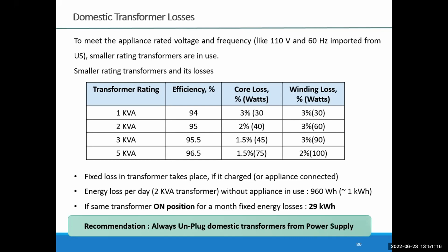Okay, so you're saying that a 5 kVA transformer will lose around 75 watts? A 5 kVA transformer has about 3.5% losses at full load. 1.5, well, no, I'm combining the 1.5 plus 2. Yeah, that is the total losses. That means when we are utilizing this transformer at 5 kVA full capacity, the total loss will be around 3.5% of 5 kVA.